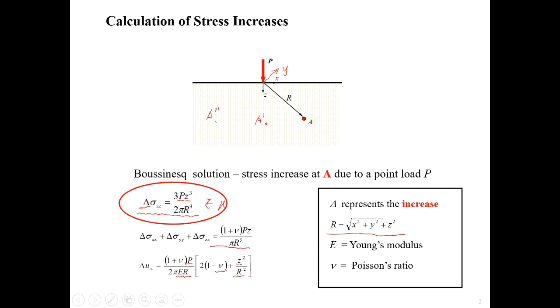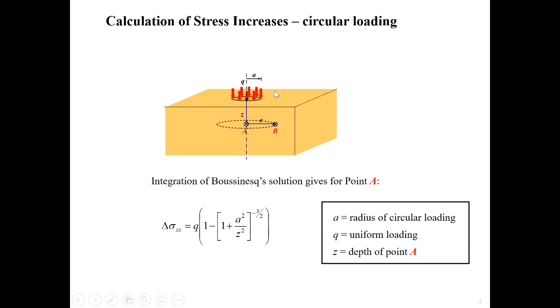So how about for the circular load? If the solution for the point load is integrated over a circular area, then the solution of the stress increase at this point A, which is directly below the center of the circular load, so if you do the projection, that's the center of this circular load, could be obtained and expressed as this simple analytical solution.